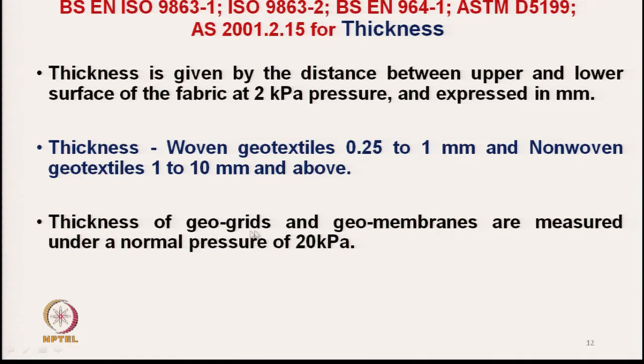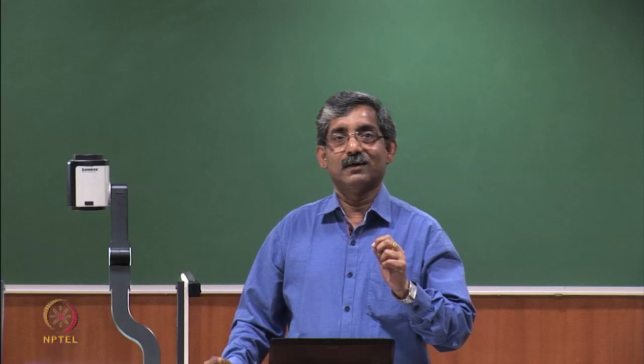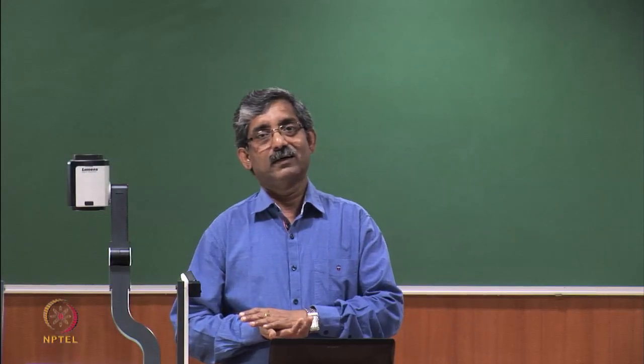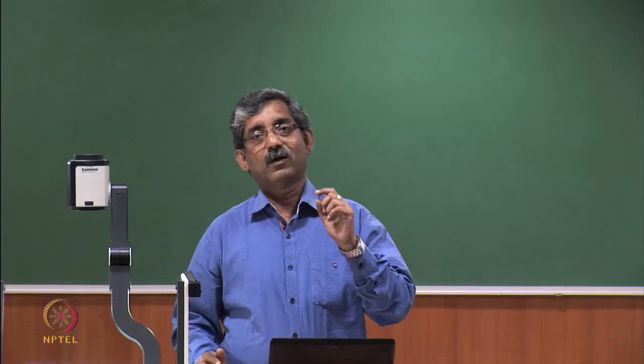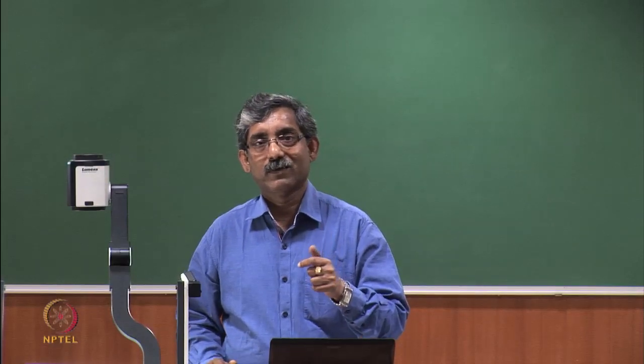Thickness of geogrid and geomembranes, which are not so compressible, is measured at a pressure of the order of 20 kilopascal.